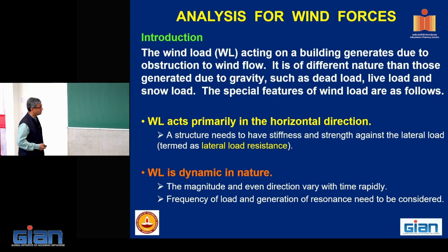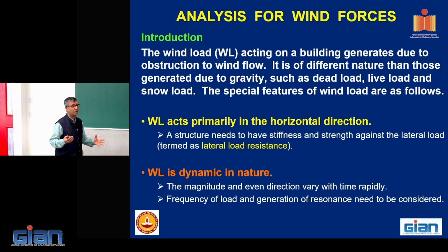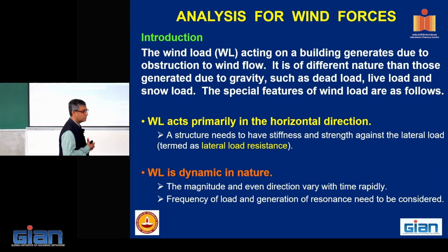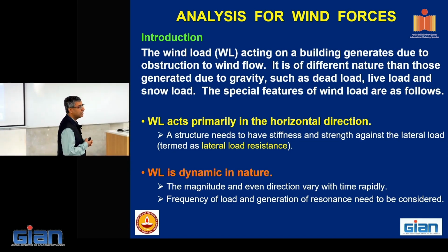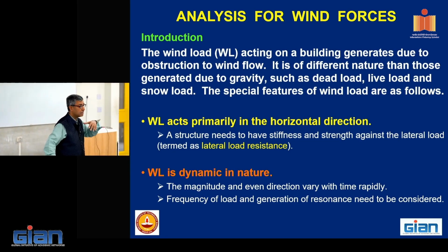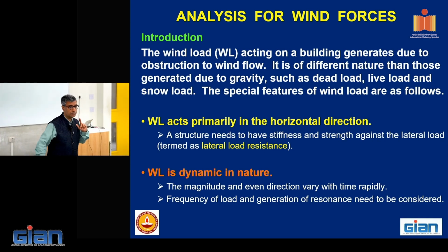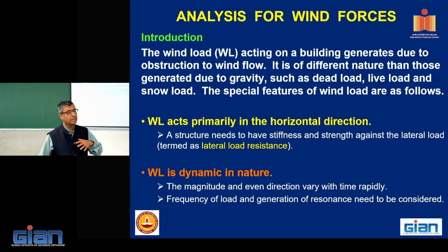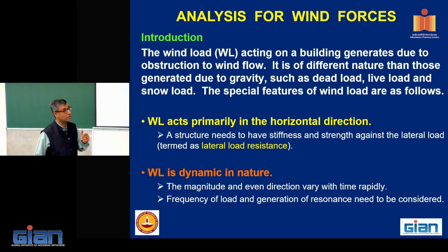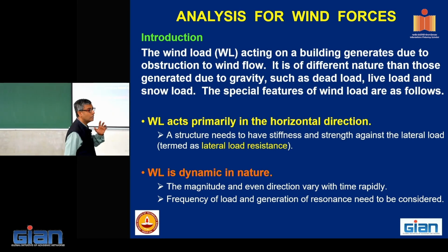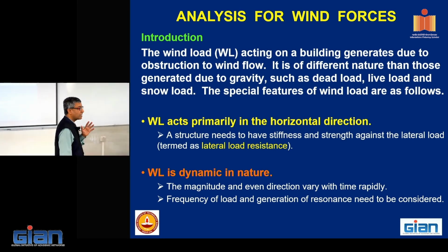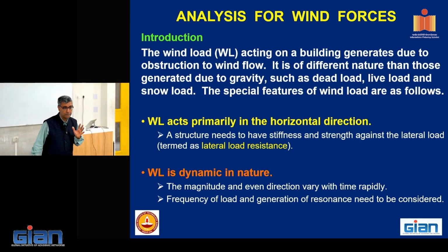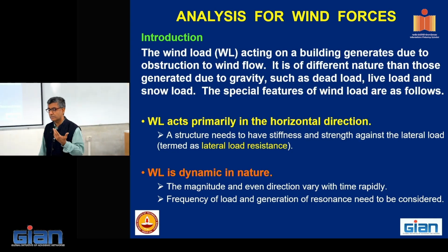Now, coming to wind. Many times our engineers have the wrong conception that if we design a building for gravity loads, since there are safety factors, it will take care of lateral loads. This wrong conception can be very treacherous for precast buildings. No. Safety factors are not to cater to lateral load. Safety factors are to cater for the material variability and the variability in our modeling.